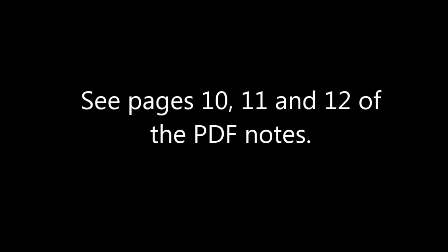If you have a delta, then you can convert that delta to a Y, or if you have a Y, you can convert it to a delta. So you see equations like this in your textbook. I think this would be page 10. So don't think that it's always a delta or Y, but if you get something like this, where the relationship is not in series and not in parallel, you might think about a delta to Y conversion. It's just a matter of going and getting the equations.